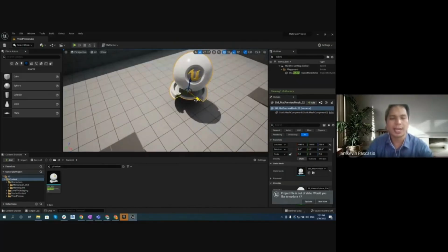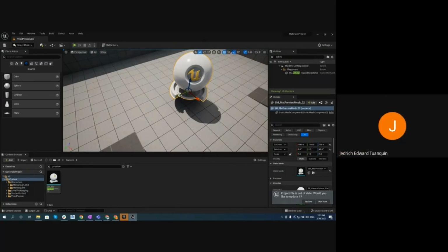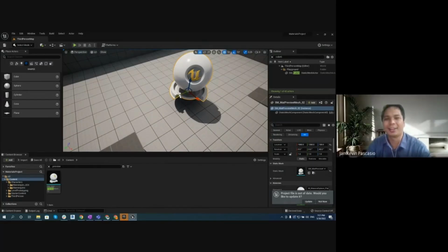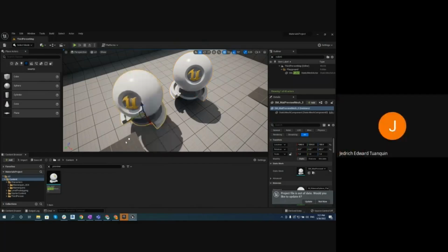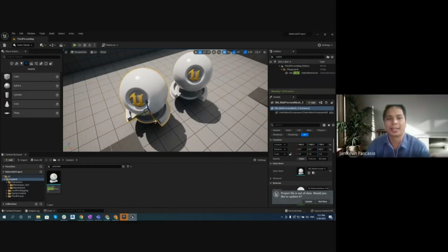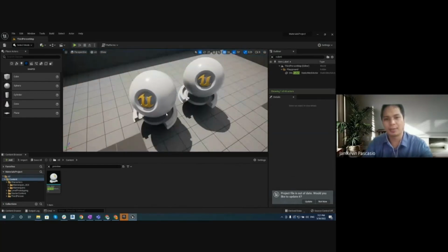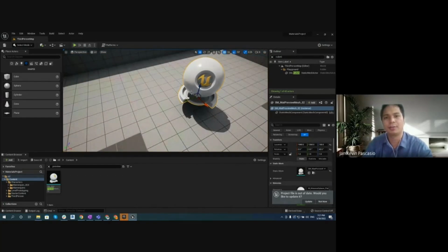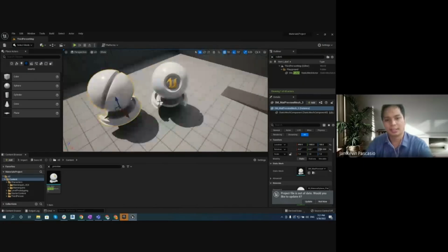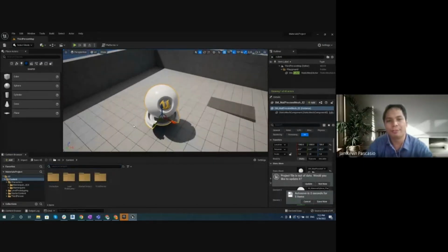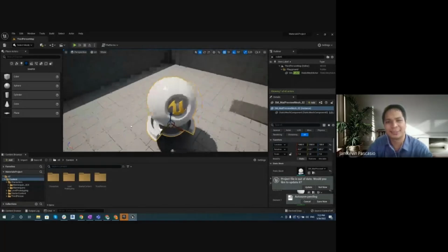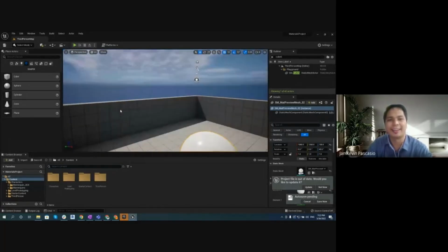You can hold the alt button, and then click and drag in one direction. So you'll see you are automatically copying or duplicating the object. As simple as that. The same goes for rotate. You can also duplicate by rotate: hold alt, and then now you have two assets.